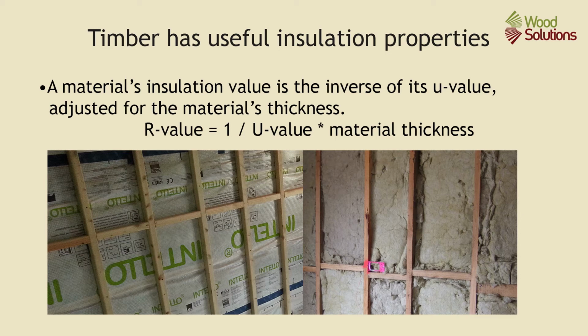Hardwood and softwood have useful insulation properties, especially when compared to other major building materials. They have a higher R value. This chart shows the thickness of material needed to achieve the same level of insulation or R value as a 100 mm thick softwood panel.